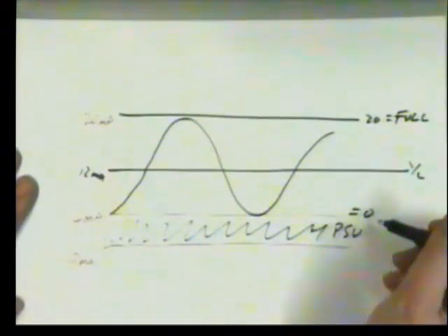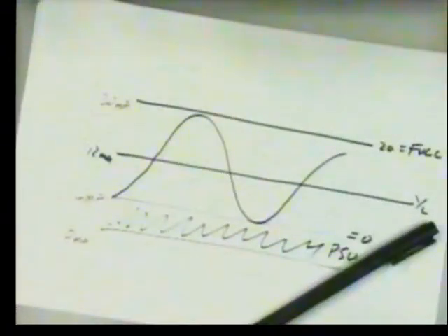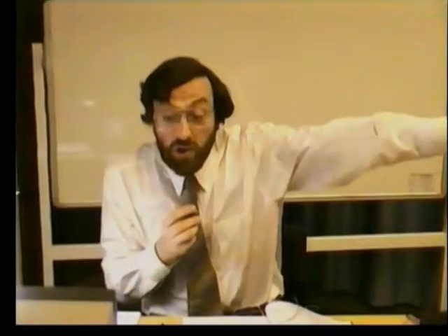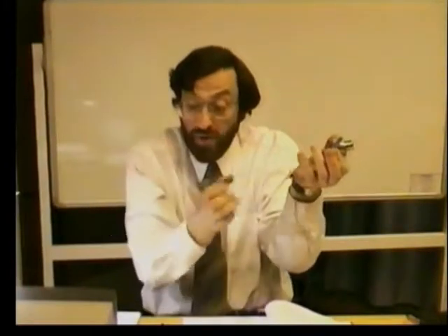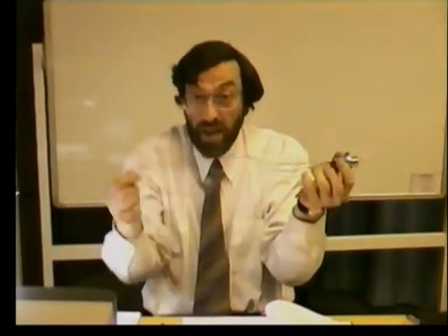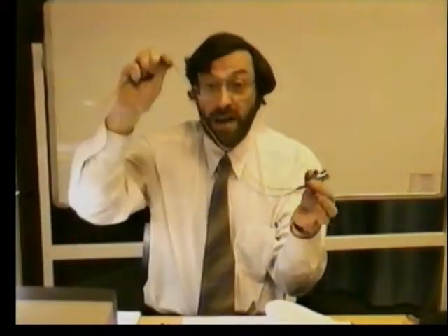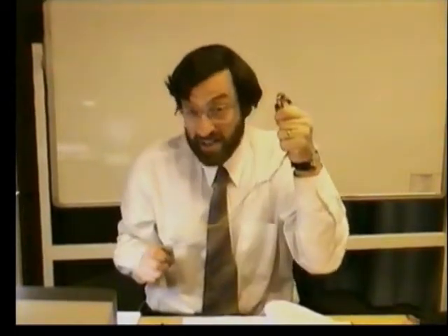So if you measured back at the computer how much current is being drawn out of the battery by the remote transducer, so here's our transmitter a long way away, if it's only drawing 4 milliamps, it means we're at 0. If it's pulling 12 milliamps, it means it's halfway. If it was pulling 20 milliamps, that was full scale. So the amount of current that is drawn by the remote transmitter is directly proportional to the variable, the measurand, we are trying to sense.